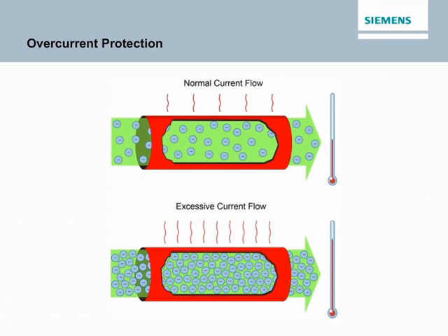Load centers use circuit breakers to provide protection against short circuits and overloads. Most residential circuit breakers do not provide ground fault protection. A short circuit occurs when 2 bare conductors touch, causing the resistance between the conductors at that point to drop significantly. This reduction in resistance causes current to rise quickly. An overload is typically a much lower current than a short circuit. An overload occurs when too many devices are connected to a circuit, or when electrical equipment is made to work beyond its rated capabilities.